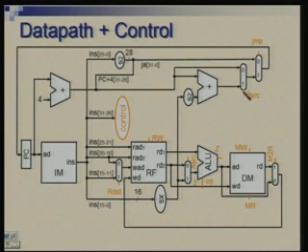So, except for controlling ALU, from these 6 bits we can derive all the information. Out of the 11 signals, 8 can be straight away figured out using these. Of course, generating this will require us to look at Z also, right.